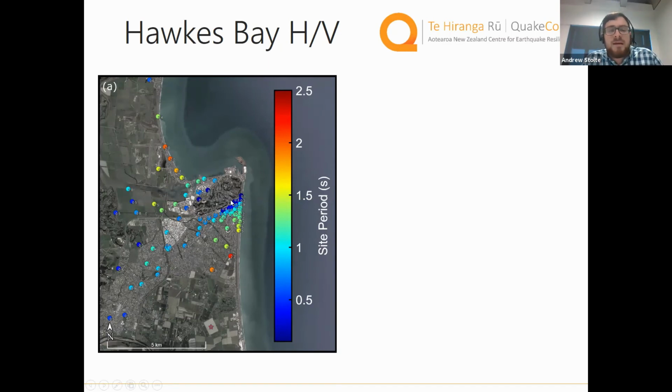And what I'd like to highlight again is that the psi period is going to be our rough proxy for bedrock depth. So near the Bluff outcrop, as you would expect, the psi period is quite shallow, around 0.1 to 0.6 seconds. And as you move further to the south towards Meeanee right here, we get psi periods increasing up to 2.2. This is relatively shallow compared to the Canterbury Basin, but still quite deep. Again, we're also getting deeper psi periods up to the north in the Bayview area.